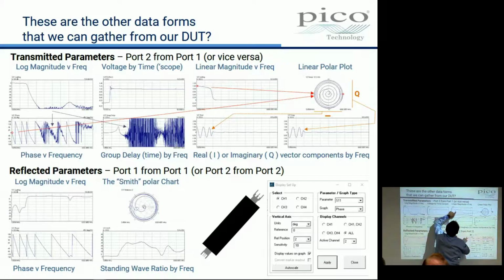When we get to this point here, magnitude starts to fall away. So this is saying we're going round and round this circle, and then it starts to spiral in to the middle. And by the time we get here, we've got no signal and we're there. So that plot is a plot of the same information, and it enables us to see how phase moves.